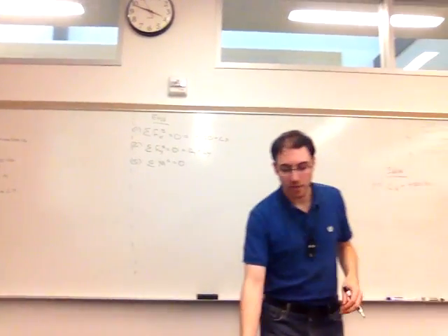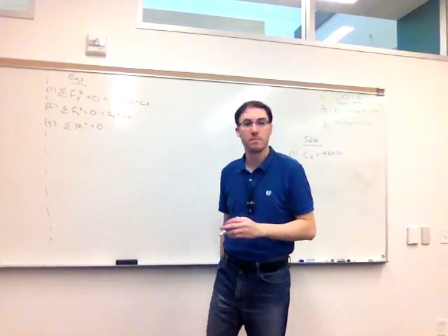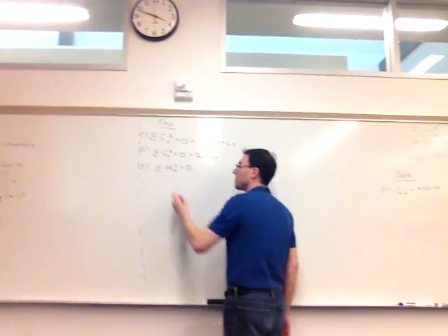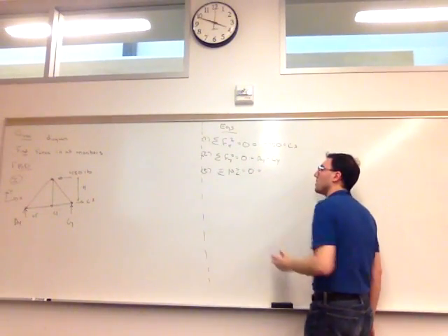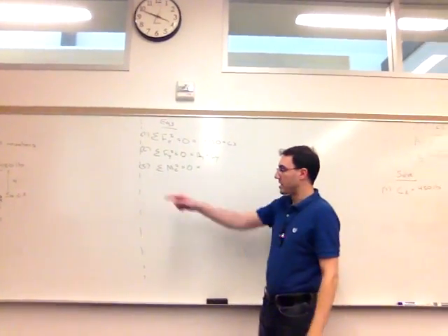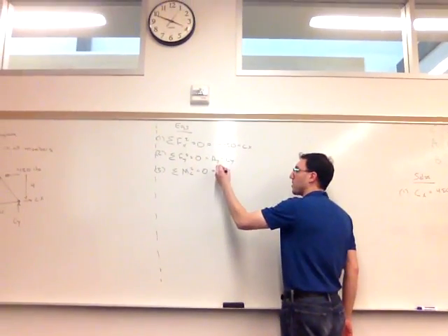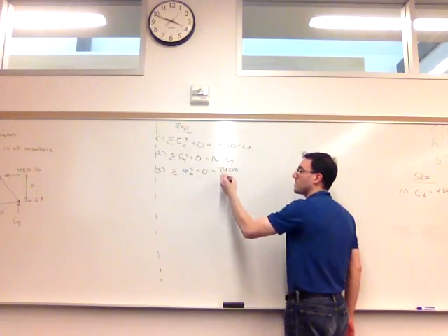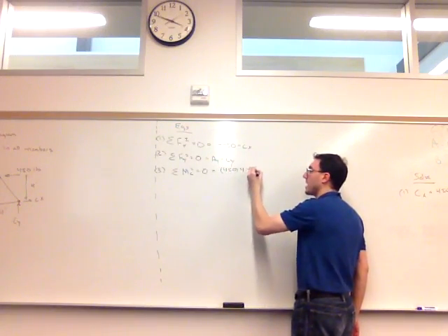So what's the easiest point to use for picture number 1? Right, the pin at C. So if I use C, then my moment around C is going to be 450 times 4 feet minus 8 AY.